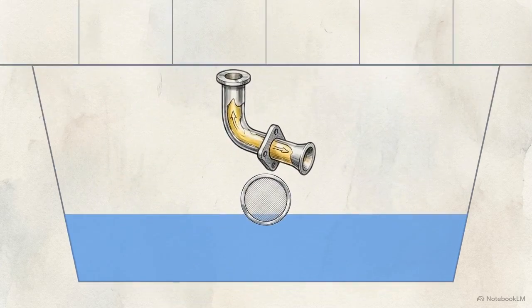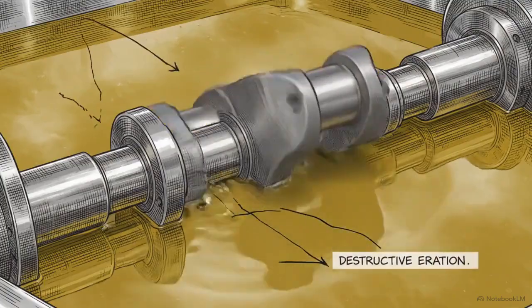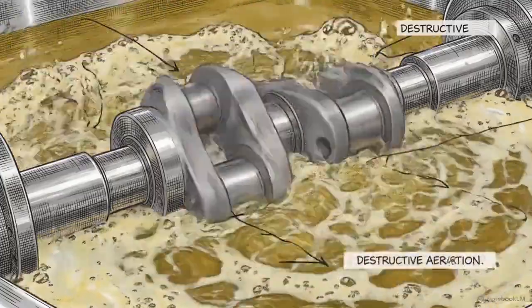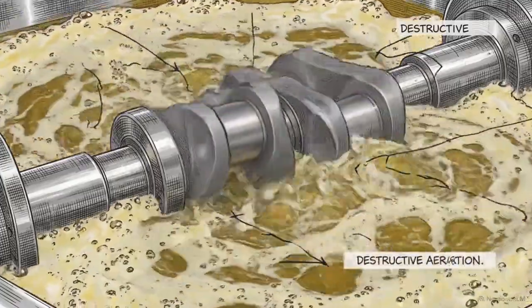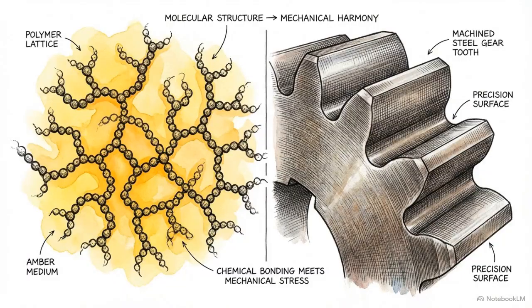Precision is critical. Underfilling the sump will starve the pump inlet of fluid. Overfilling it allows the rapidly spinning crankshaft to strike the fluid reservoir, whipping the oil into an aerated foam that the gears cannot pump. The lubrication circuit is never a permanent installation. It is a highly active, slowly degrading system. Keeping an engine alive requires perfect continuous harmony between fluid chemistry and strict mechanical regulation.